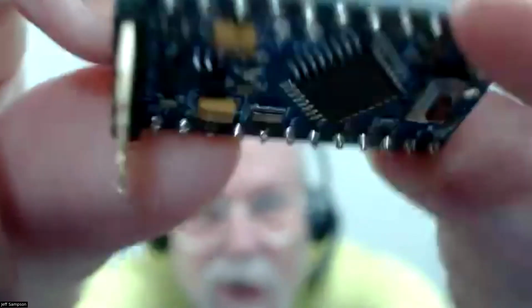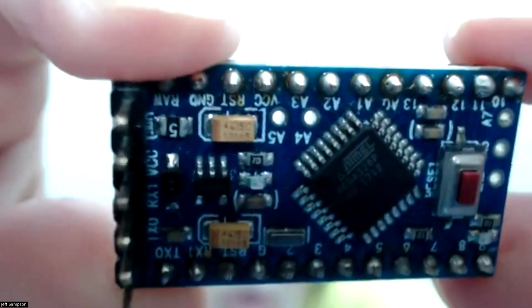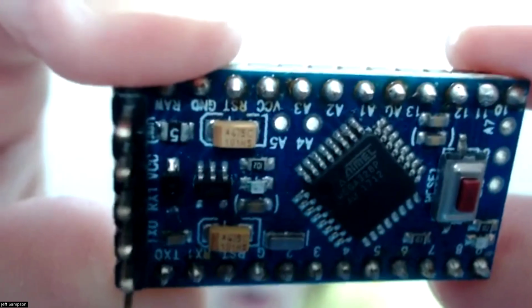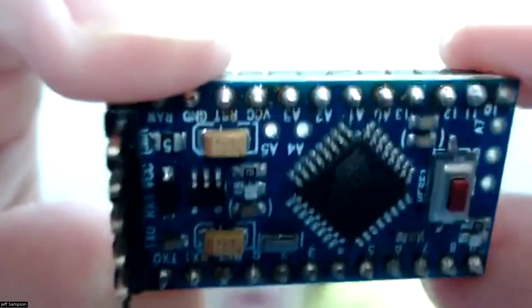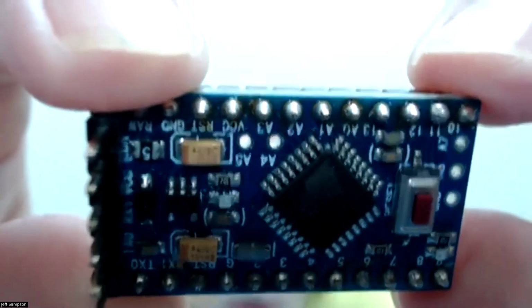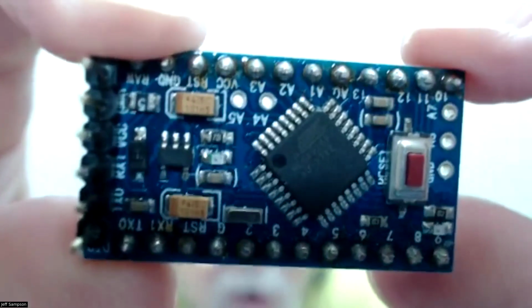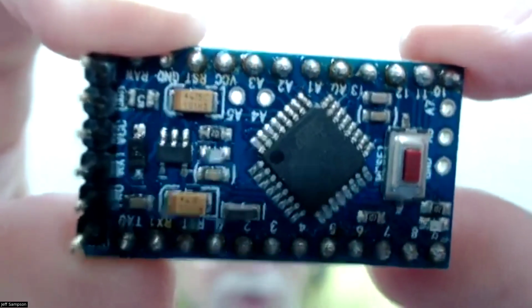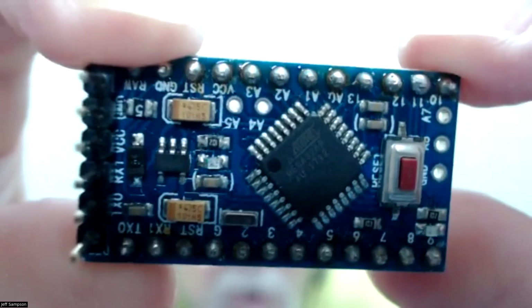And on the front of it, on the upper left there's a resistor that has a 5 on it. I assume that means it's a 5 ohm resistor. So probably if you pull that resistor off the board, that would be the same as unsoldering that solder blob. But nobody's figured that out yet. Right in the middle, there's that 5-pin regulator chip. The one guy had a hot air gun and tweezers, and he's pulling that off there.